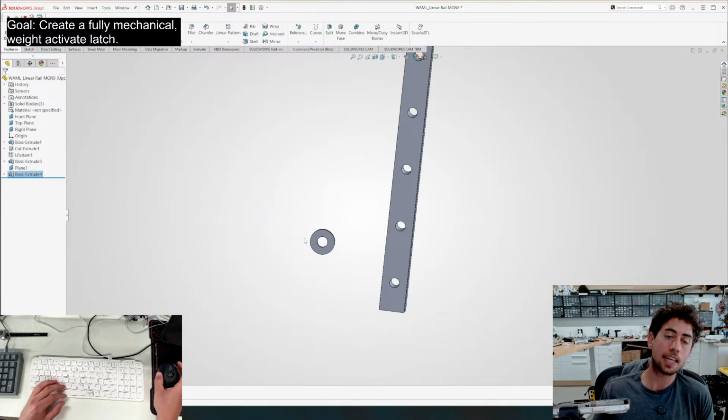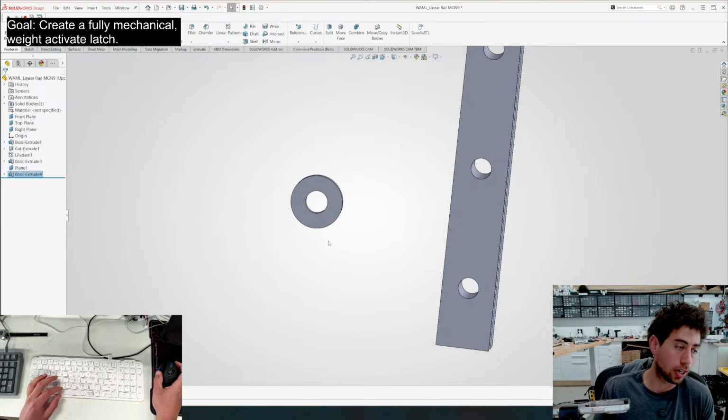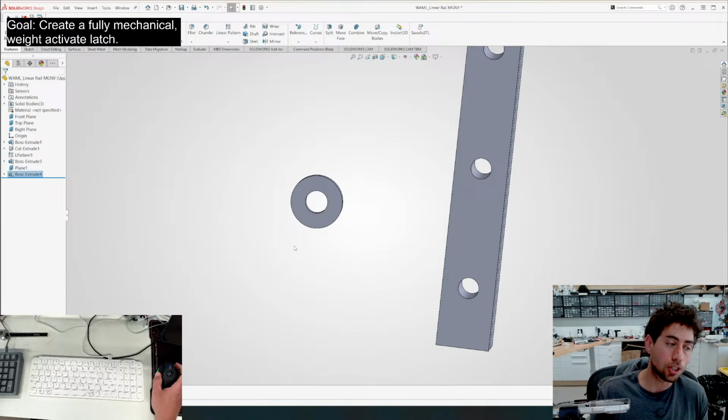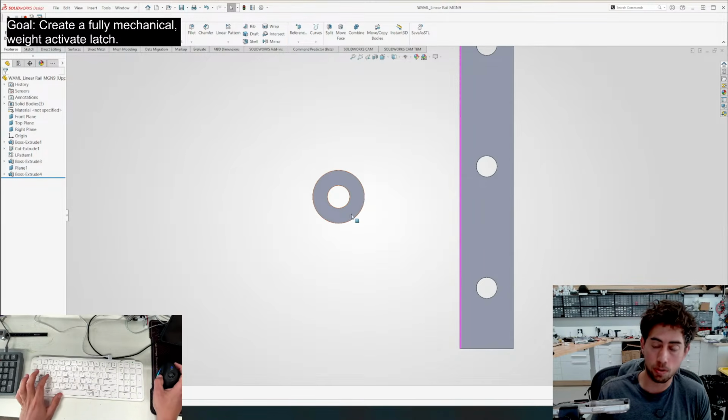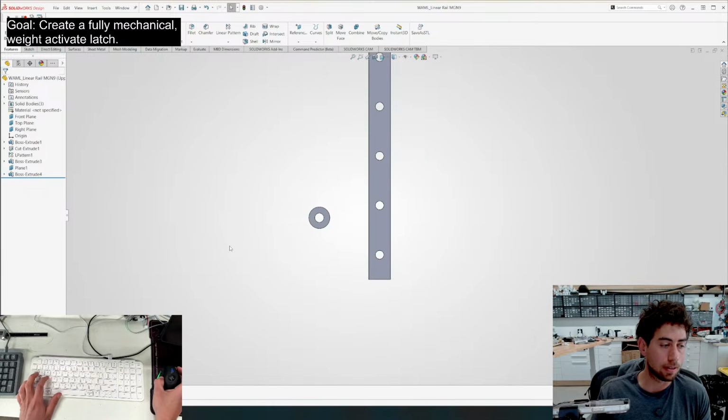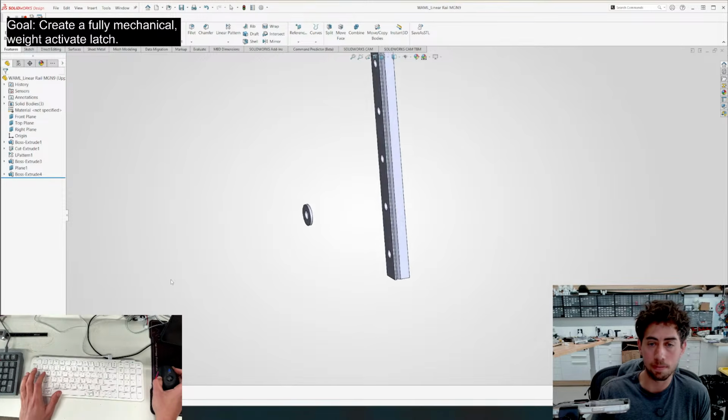Because technically I can make this any dimension I want, right? But if I make this thickness 2, and I'll show you this later, the way that it prints is a little bit weird. If I make it 1.8, that ends up being 1, 2, 3, 4 layer lines on a 3D printer, and that's actually very clean. 2.5, you get 1, 2 layer lines, then a thick infill, and then 1, 2 layer lines on the outside. So stuff like that is pretty important.